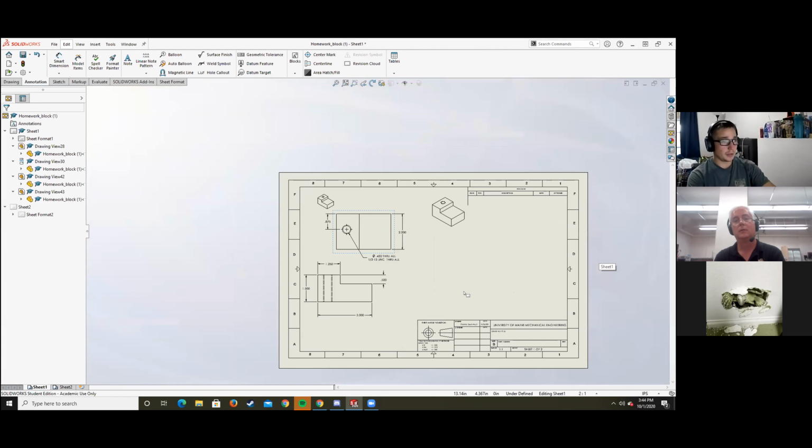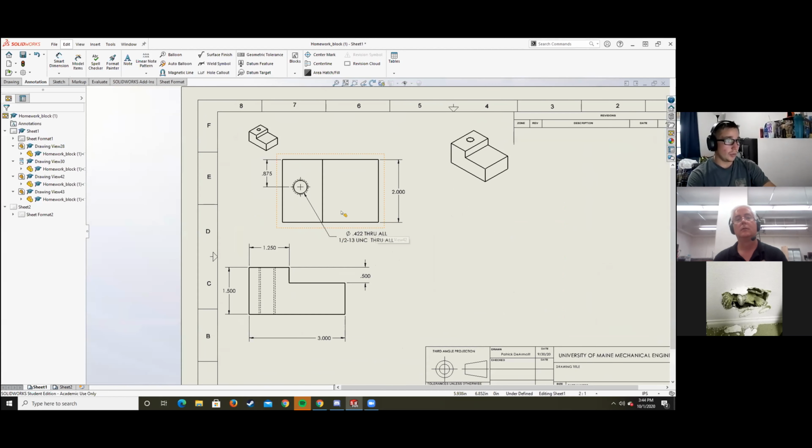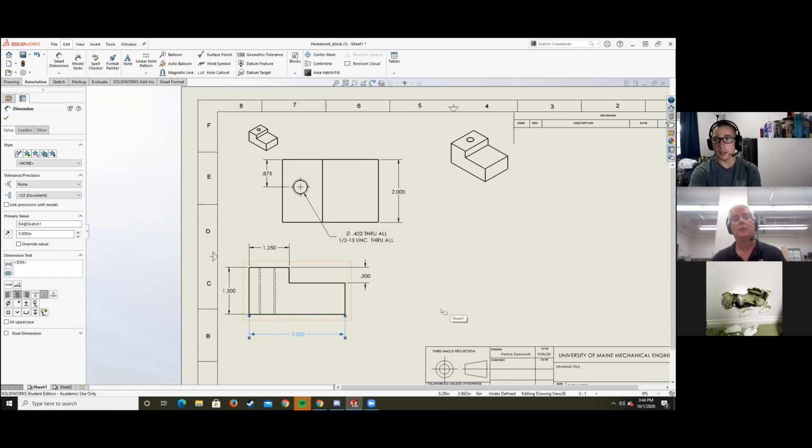And I know, like what you were talking about, is almost. I really don't want to add any more dimensions to this top one because as soon as I do that, then it's going to be redundant of this. Because the only other dimension I could add here is like this dimension or this dimension, or no, or the whole length of it. But I already have that down here, so that would be redundancy, right? We don't want that, right? Correct. You never want redundancy.